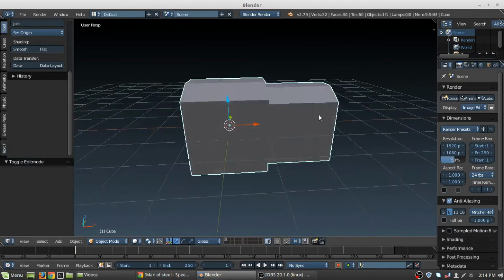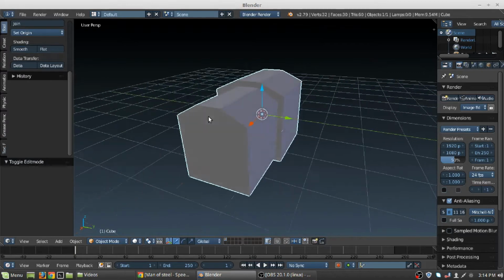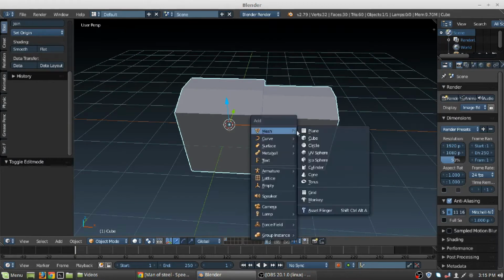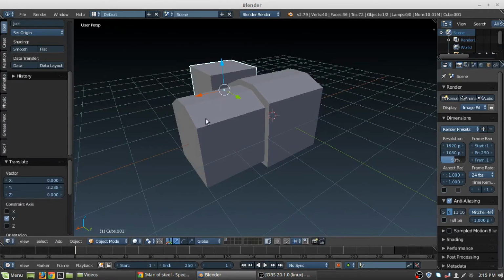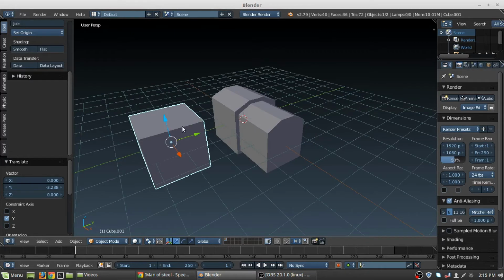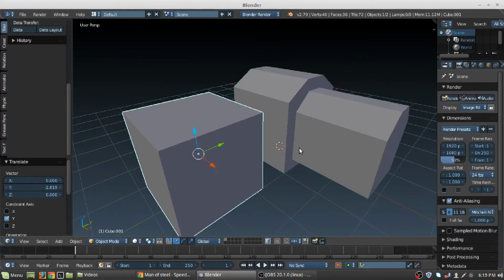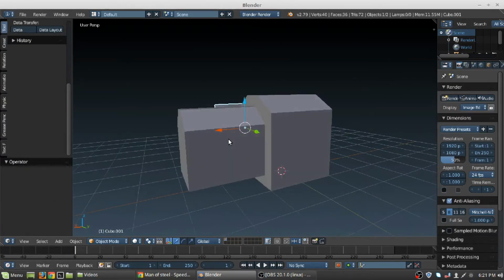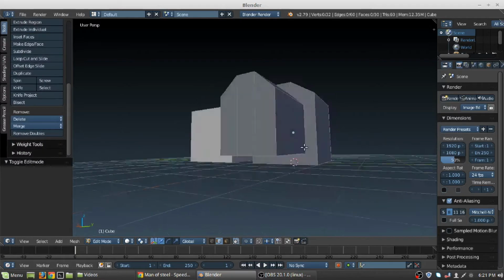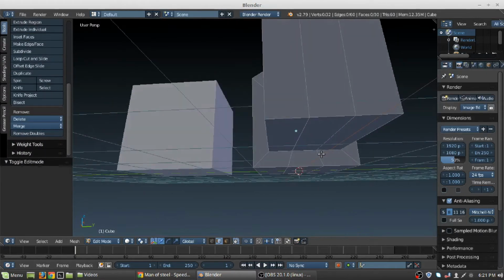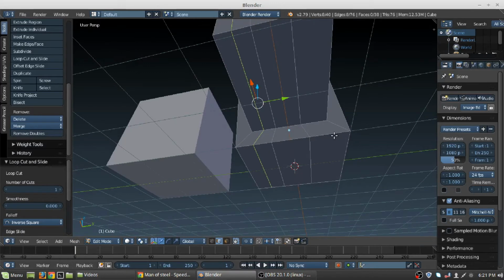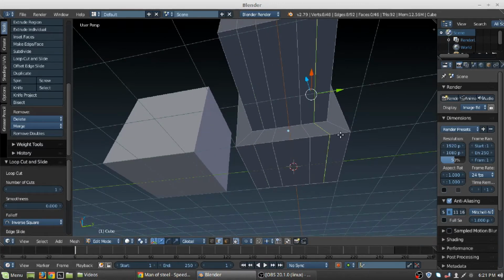As you can see, we have changed the entire shape of the model, as we were given just a box previously. We had this box and we have changed the entire box into a different sort of shape. This is how modeling is done. Let's edit this model further to create a more different shape from this. Let me create one more loop here by pressing Ctrl R, and one more loop here by pressing Ctrl R and then left clicking.